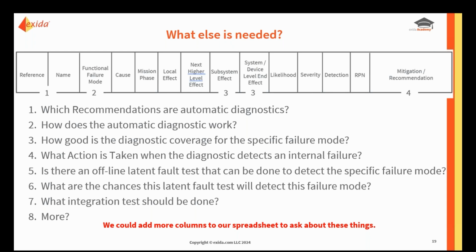Obviously, a diagnostic that lights an LED on the PC board is going to be essentially useless compared to a diagnostic that puts an annunciation signal out or puts the device into its fail-safe state. Are there proof tests or latent fault tests that can detect the failure mode? Again, what is the effectiveness or coverage of that latent fault or proof test?